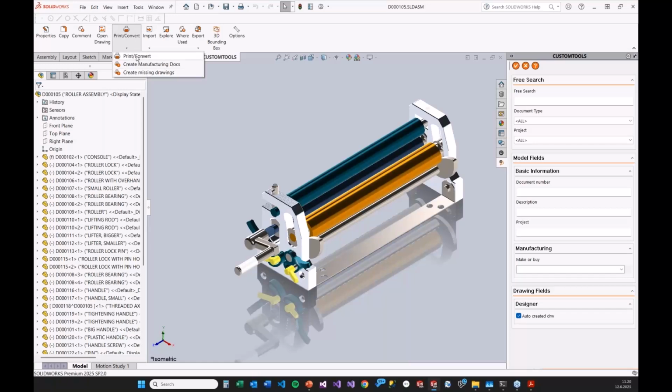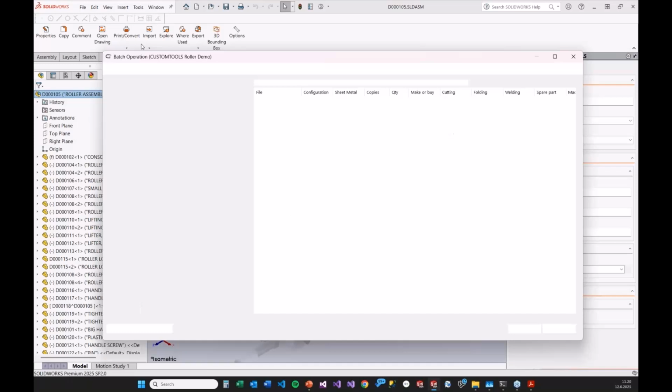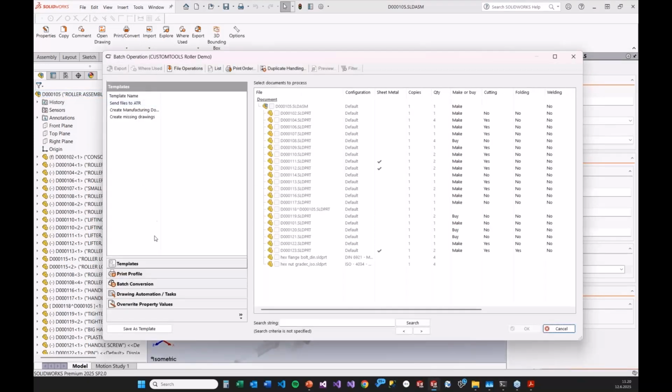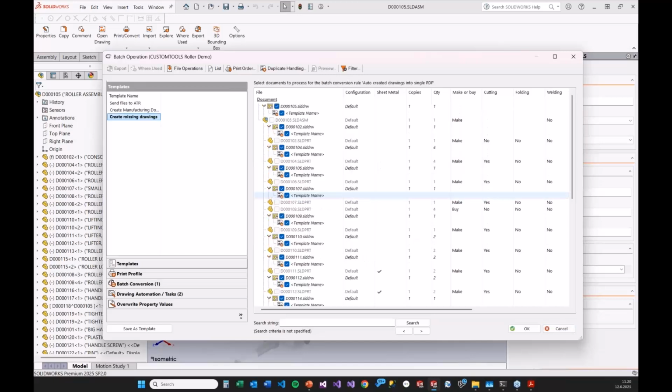But if you do it the conventional way in SolidWorks, you could open the tool and go to templates, where we already are, and just activate the rule and confirm that we want to apply these rules. So now everything is applied here, and I could just say OK, and it's good to go.